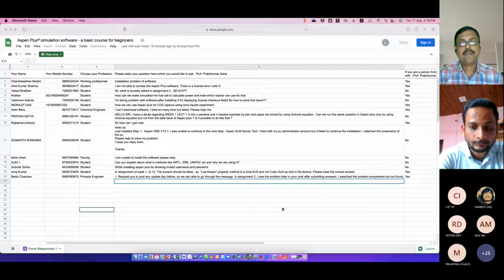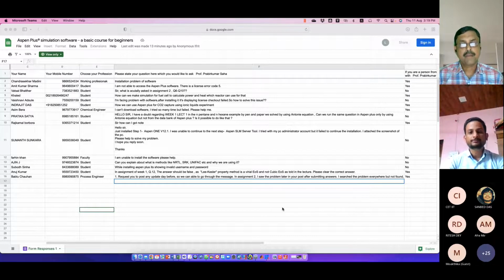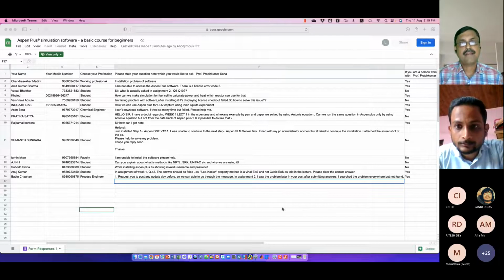So it can give you certain guidelines, but you may have to try out various property methods, similar types of property methods, and check which one is giving you the most appropriate result compared with what you have obtained through your experimental method. That property method will be ideal for you. If you still have some difficulty, you may consult the property method assistant.